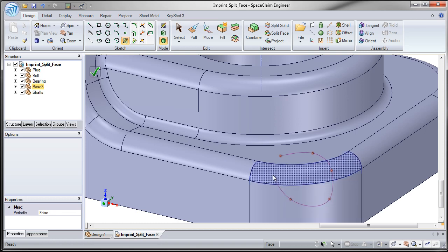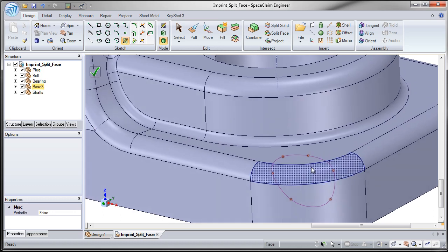Now you can switch between faces that are there, and when you click the starting point, it makes this complete spline. Now you can drag on these points and reposition them on your model, but notice if you go too far, if it gets too crazy, it might not actually be able to make this spline. And then it's going to show you that it doesn't exist anymore. So if you want it to be a little bit crazier, you'll have to have more spline points that are driving it. Whenever you're ready or finished, or you'd like it, you can click the check mark on your screen, or you could hit the Enter key on your keyboard.